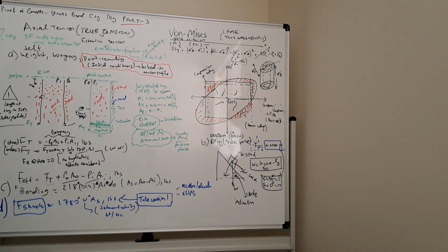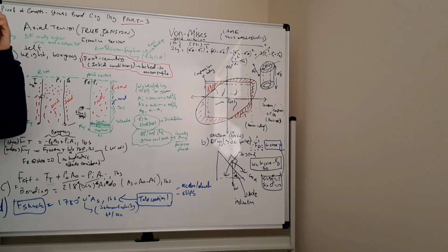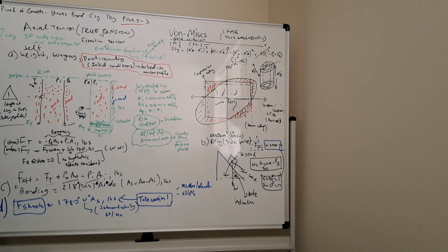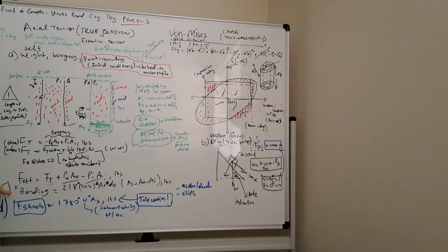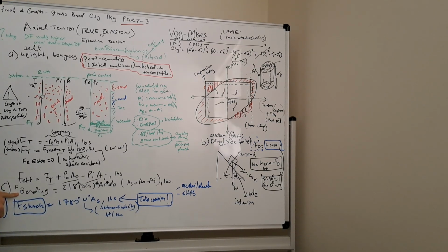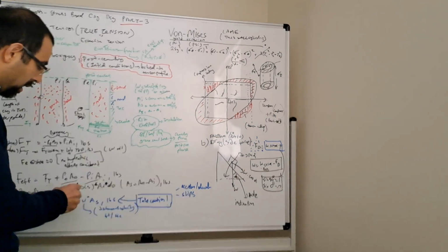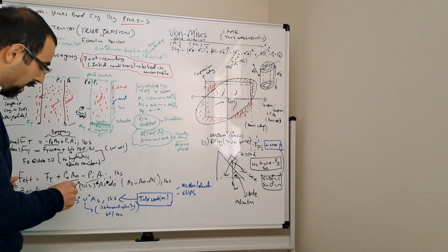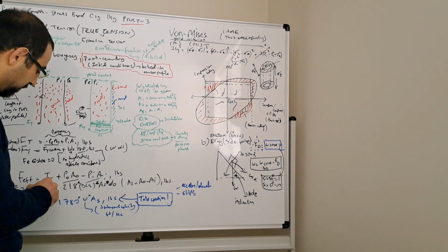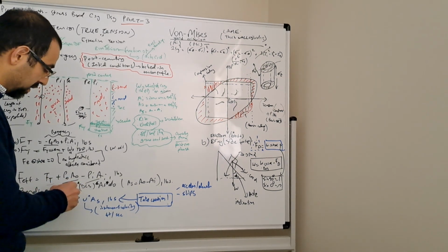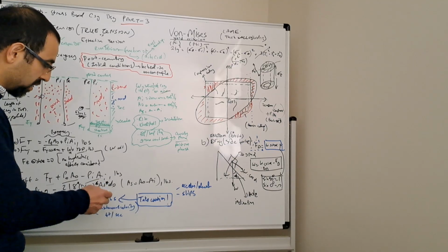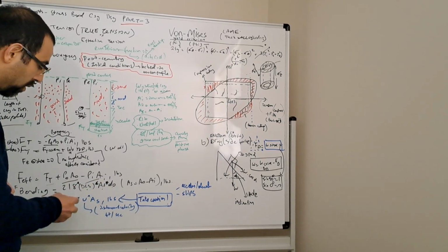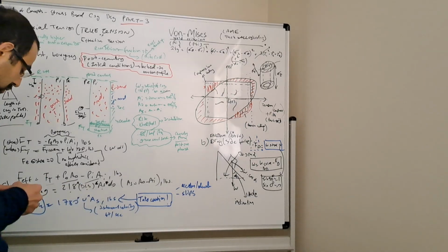The next one I'm going to talk about is the bending. Of course, in a vertical well, I'm not sure if a completely vertical well exists in the world, but if you have a well with dog legs in a deviated hole, then the equivalent axial tension resulting from this dog leg is basically calculated with this equation. So there's the outer diameter, cross-sectional area, dog legs, and then there's a conversion into pounds.